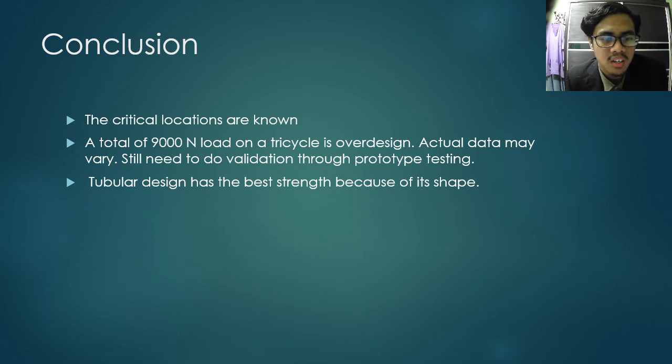Another thing is although a total of 9,000 Newton load on the tricycle is over design, which is very high, it is done to ensure the safety factor of the tricycle. But the actual data may vary. We still need to do validation through prototype testing.